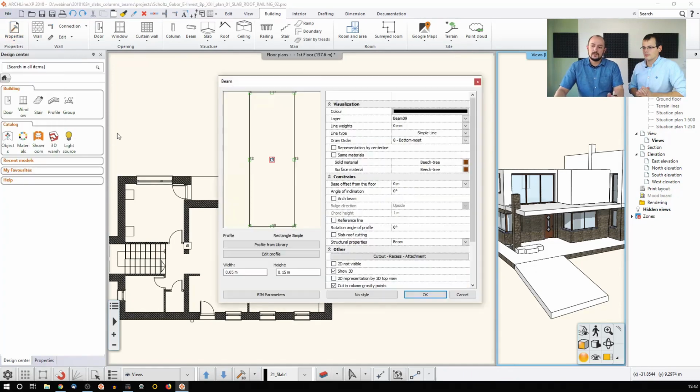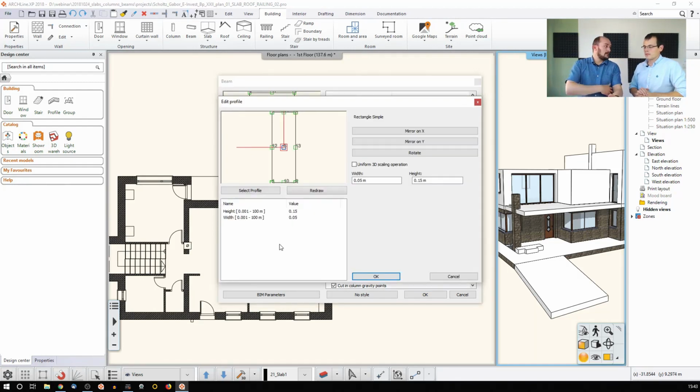But either way, you can check what you will create and you can change their cross-section profile and all of the settings. Talking about the settings in general, all the beams have a cross-section which you can select from a larger library. The software is shipped with a library of cross-sections, and you can even create your own cross-section.